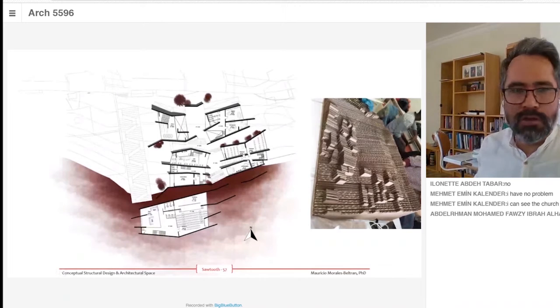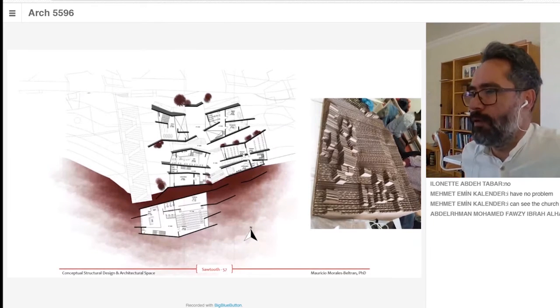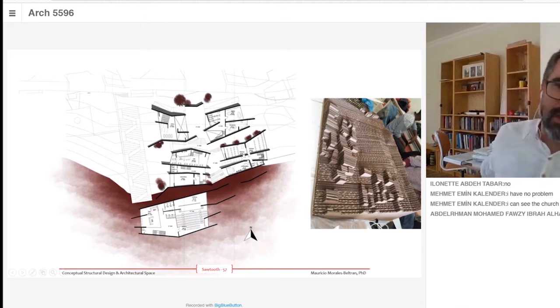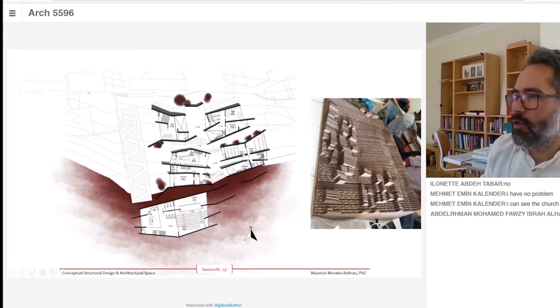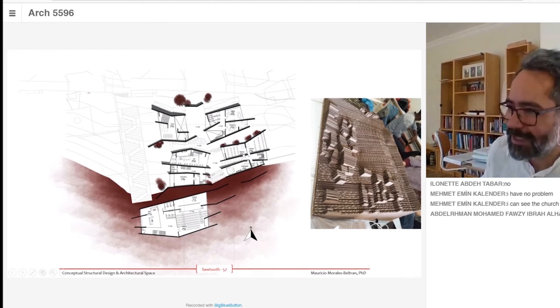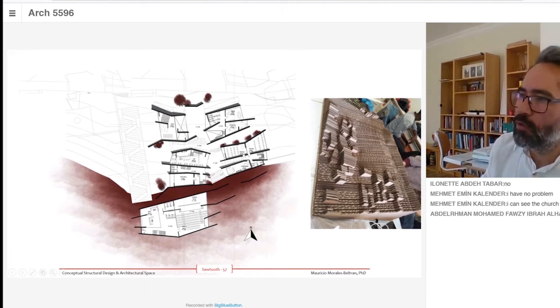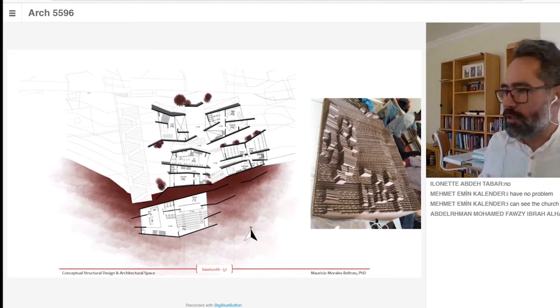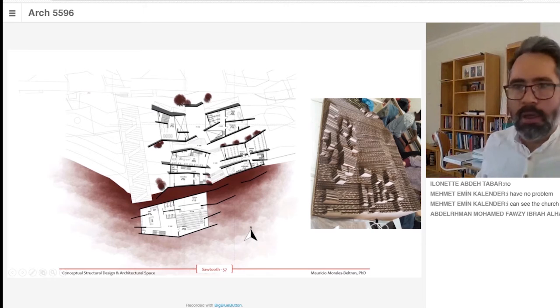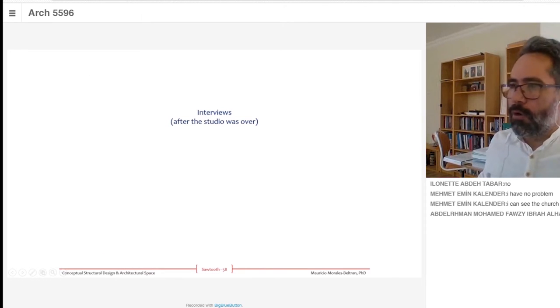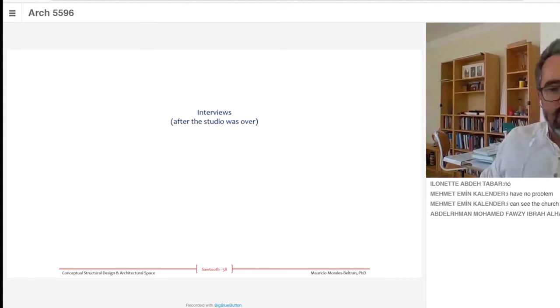If there is any seismic engineer among you, you would say, yeah, but you have walls mostly in one direction. Yes, it's true. So we have to add very huge beams in the other direction in order to make some sort of frames, moment resistant frames in the other direction to balance this distribution. So I'm going to quickly go over the conclusions, which are not many, so then we can make a break.